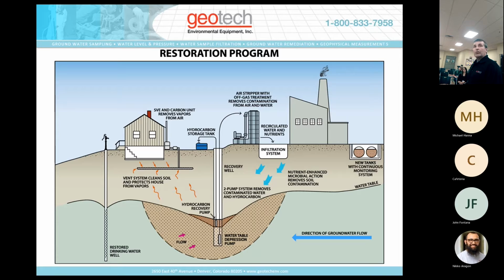So with the soil contaminated, the fumes can get into someone's basement, and so we use blower systems with this section of piping to basically draw a vacuum in the soil and transfer the contaminants from the soil into the blower and the discharge and out to a treatment system.